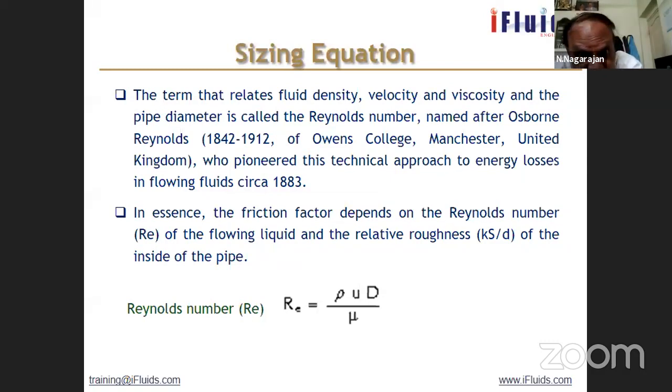After the actual piping is done, we will have the exact fittings count. At that time, we redo the line hydraulics after the piping design completes the plot layouts and then the isometrics. Based on the final isometrics, we will know exactly the number and type of fittings. You can fine tune your hydraulics.